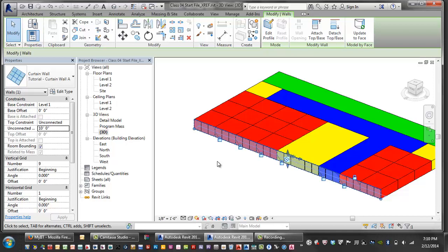So case B is more prevalent nowadays than it used to be, and what this area is called is generally either a slab edge cover or spandrel glass. So you can do either or. Typically in A, you'll have a slab edge, in B, it'll be spandrel glass. Because you want to cover the edge of that slab because of thermal breaking. You don't want to have any elements exposed that are interior elements to the exterior. Is that clear?